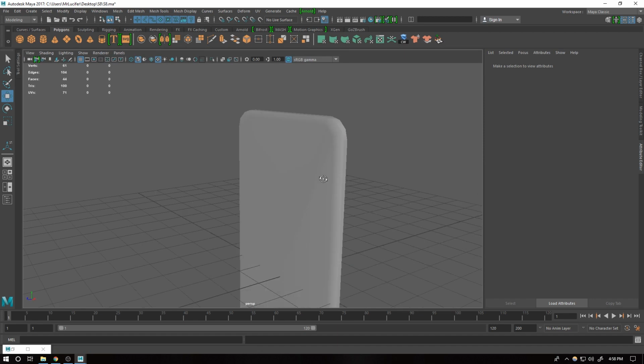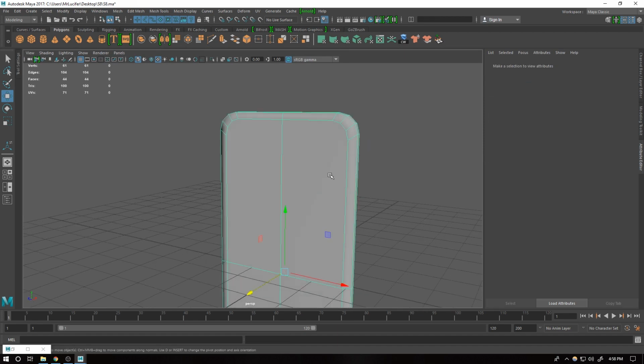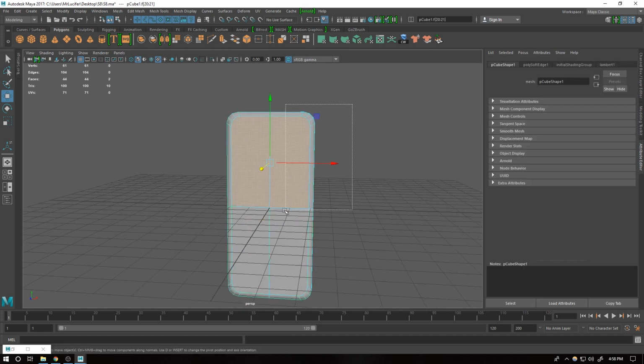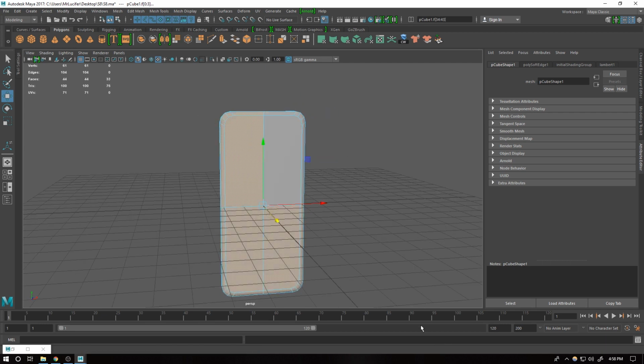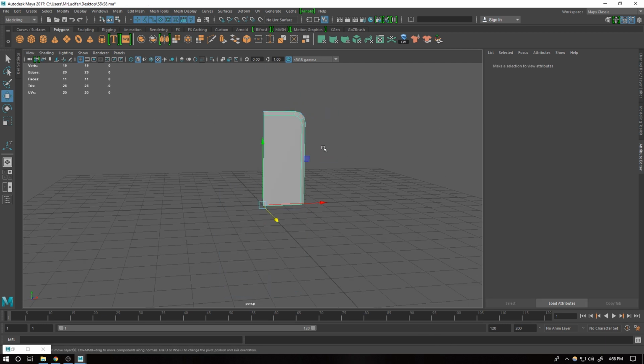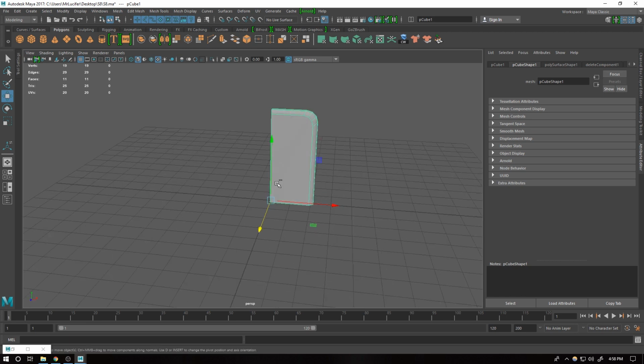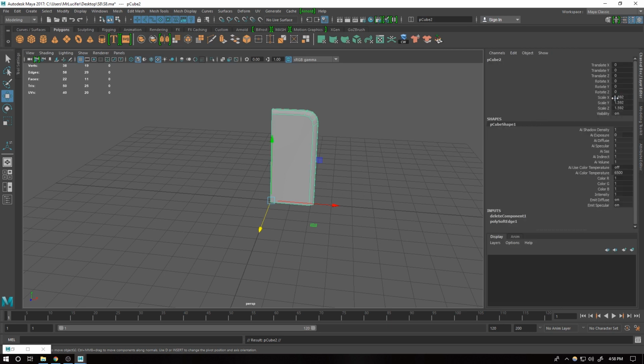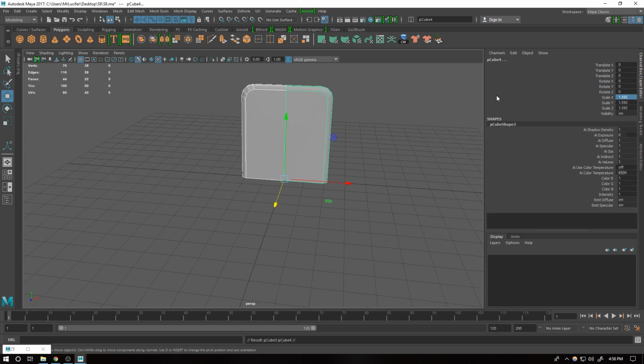So yeah, I work on this part. That's why I'm going to delete all the sides and flip this one to every side. So I'm doing Control Shift D and scaling it to -1 here, and again Control Shift D, scaling it to -Y here.